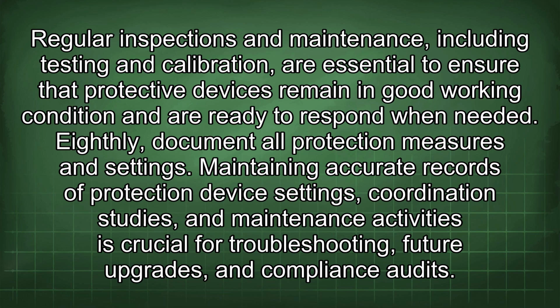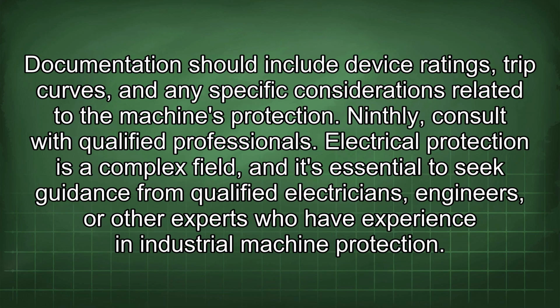Maintaining accurate records of protection device settings, coordination studies, and maintenance activities is crucial for troubleshooting, future upgrades, and compliance audits. Documentation should include device ratings, trip curves, and any specific considerations related to the machine's protection. Ninthly, consult with qualified professionals.